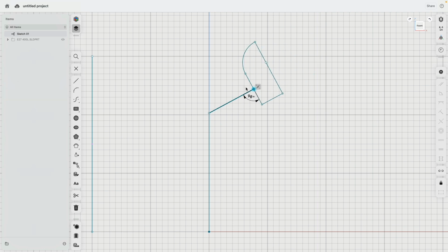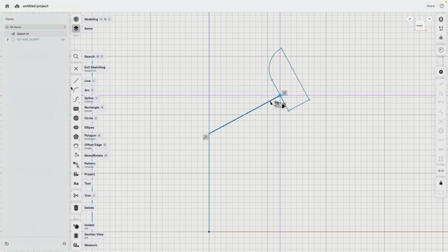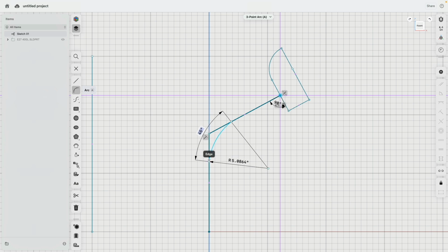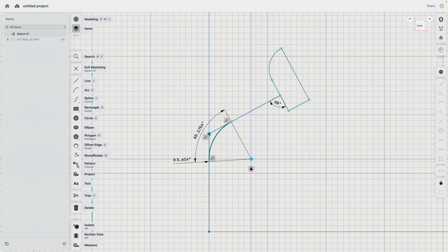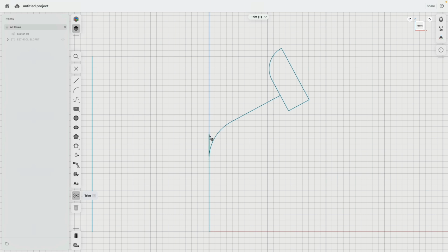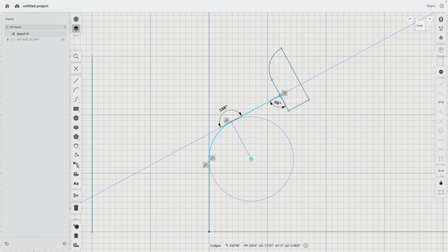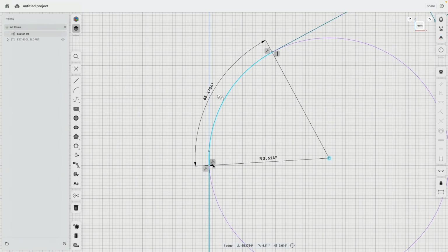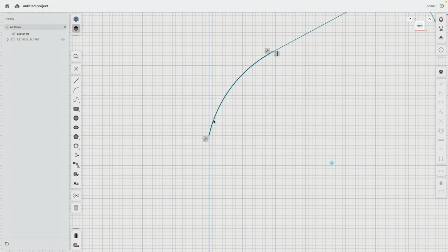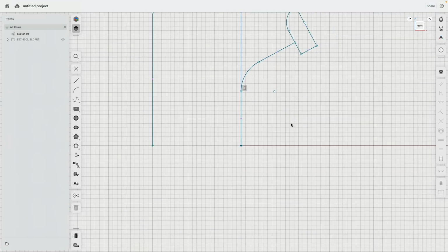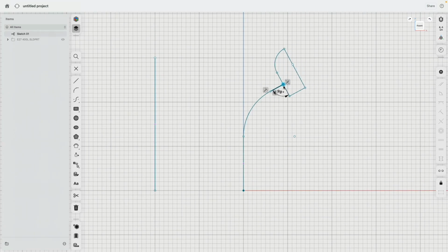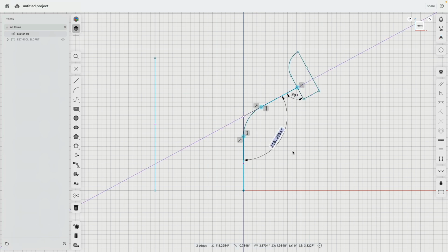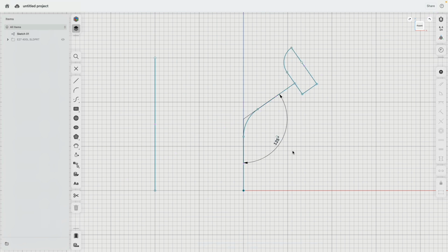This one here we can unlock. And then we do the following. I'm going to draft in an arc. There we are. Then I will trim all that away and make the arc to the line tangent. There, very good. Beautiful, because now I can move this around, and to specify an angle with that, I can now rotate it.